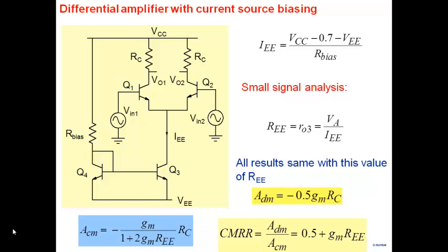As an example, suppose I put a resistor in the emitter of Q3. One resistor R here and another resistor R here. When you look down, what do you see then? You see R0 multiplied by 1 plus GM RE parallel R pi. So you will get even higher. So if you want, put a resistor here.